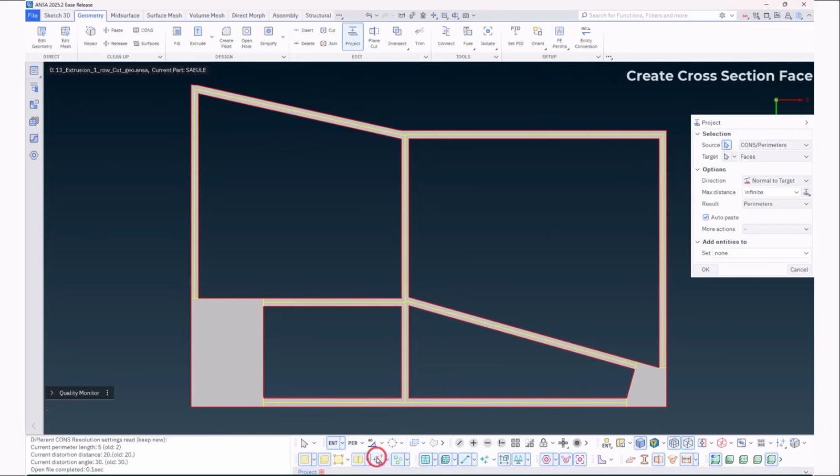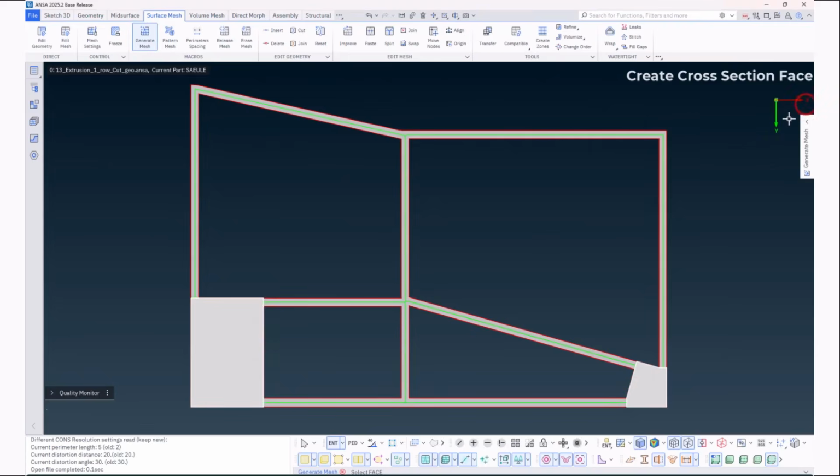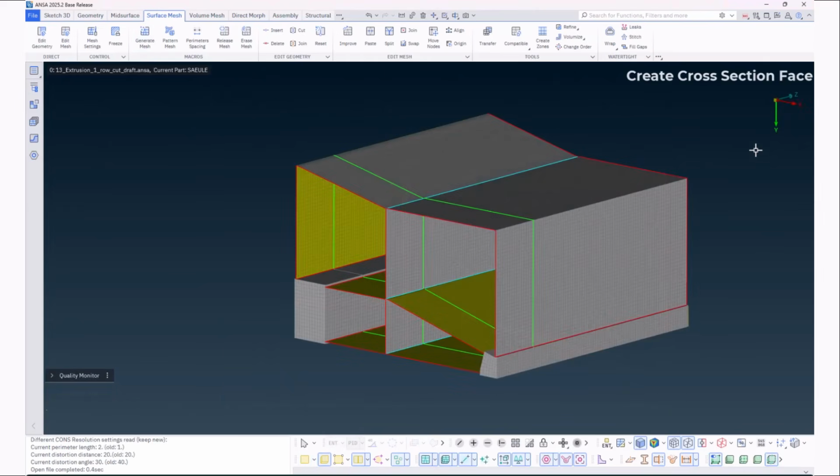The separated area can be meshed with the new forced quad algorithm, so it can later be volume extruded. The curves can be extruded to generate FE shells. When both operations are done, a hybrid mesh will be generated.